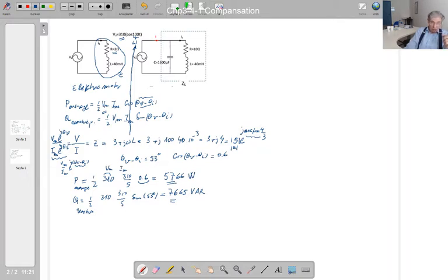So the electrical energy supplier does charge for the reactive power as well. But what they do advise is this. They say you can spend less money by making a change in your circuit, that means in your electrical motors, in order to make that reactive power equal to 0. If this reactive power is equal to 0, I'm not going to charge for that. So our aim now is how we can get that amount of power for our motor, and at the same time, how we can get rid of this reactive power.